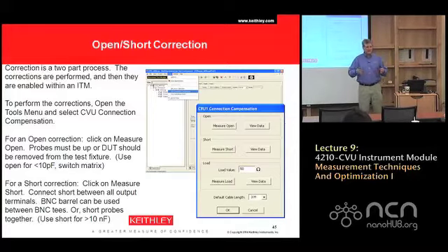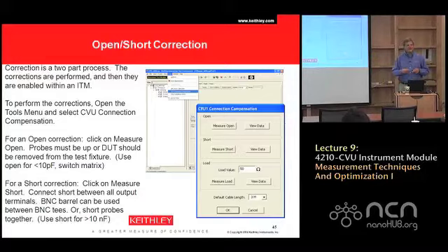A standard coaxial cable is running probably in the neighborhood of 55% of the propagation speed in vacuum. In other words, it takes a certain amount of time to get down that cable. Even through vacuum, we can only propagate a wave at a certain speed, but down a cable it's only 55%. Keithley's cables were specially designed to give us about, I think, 70% propagation velocity. But the point is this: it creates a phase shift in the cable, so we have what's called a cable length term.